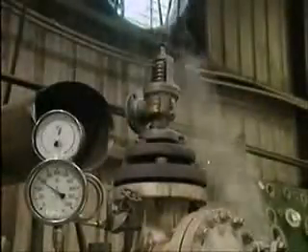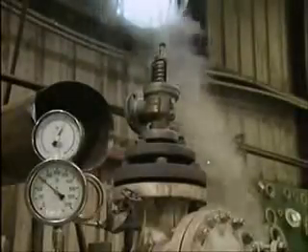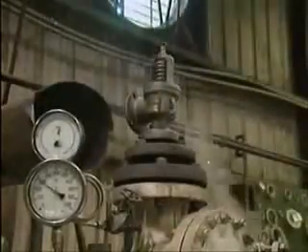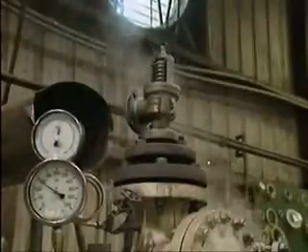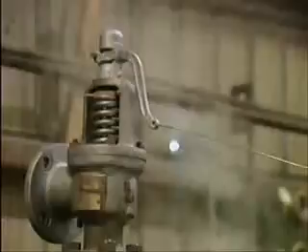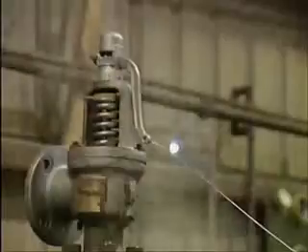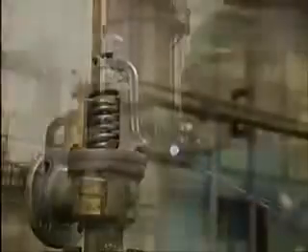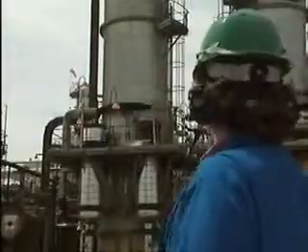An external inspection may reveal that a valve is leaking between the disc and the seat. This could occur if the valve didn't reseat correctly after the last time that it popped. Or it could be caused by foreign matter, such as ash, dirt, or rust particles trapped between the seat and the disc. In many cases, you can correct either of these 2 causes of leakage by manually lifting, or hand lifting, the valve. Hand lifting clears foreign matter out of the valve and gives the disc a chance to reseat properly. But any time a safety valve is lifted, there's a corresponding drop in system pressure.